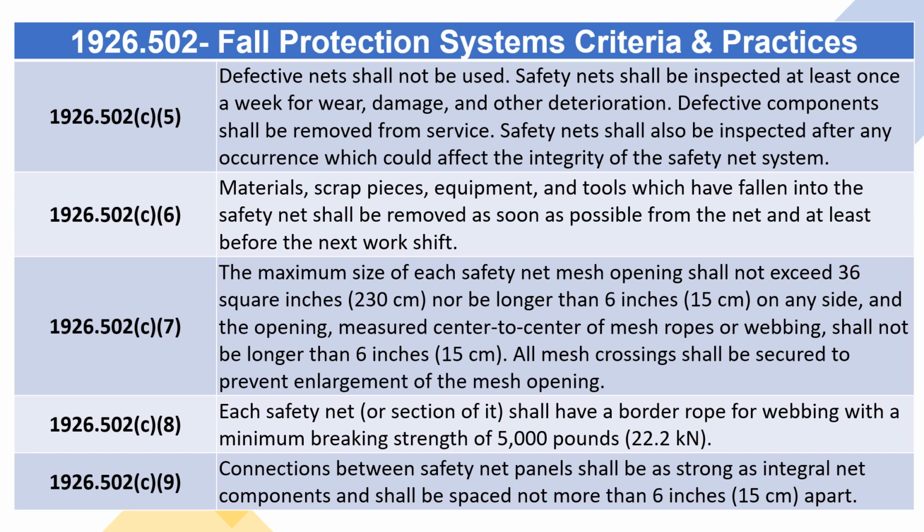1926.502(c)(6). Materials, scrap pieces, equipment, and tools which have fallen into the safety net shall be removed as soon as possible from the net and at least before the next work shift.